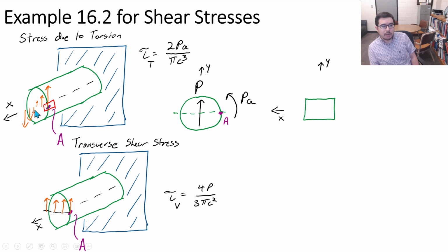Well, X is coming out of the left side, so I'm going to put this shear stress to be positive on this left side. And this is tau xy. Wait, what does that mean? Remember, if we go back to our convention and our nomenclature, the first component is the face, the x face, and the second component is the direction. That's the y. So tau xy is, in fact, upward in the y direction, in the positive y direction. And it's nice because that corresponds to what we see here as well.